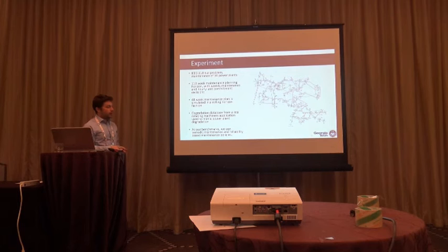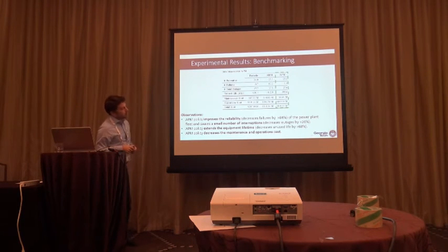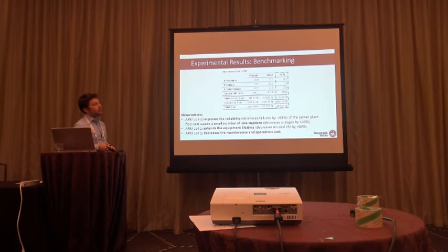And as a benchmark, we are using the periodic maintenance policy and the reliability-based maintenance policy that I outlined in the beginning of this presentation. So here's a part of our results. Our RBM is the reliability-based maintenance policy, and APM, the adaptive predictive maintenance policy, is our proposed method. And here we're looking at metrics in terms of IEEE Task Force on Maintenance recommendations.